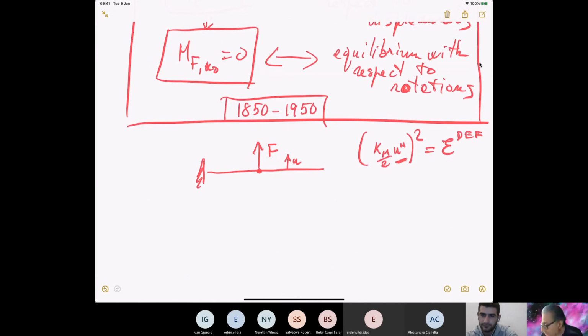We will go back to this point, to this argument. In the theory of beam, you can apply concentrated forces. Why? Because in the deformation energy, you have the second derivative. You remember, this is the curvature of the beam. If I have a beam and I'm curving it, the second derivative is changing, and to deform a beam having a change of curvature, you need to give a deformation energy to it. So the deformation energy depends on the integral of the second derivative square.